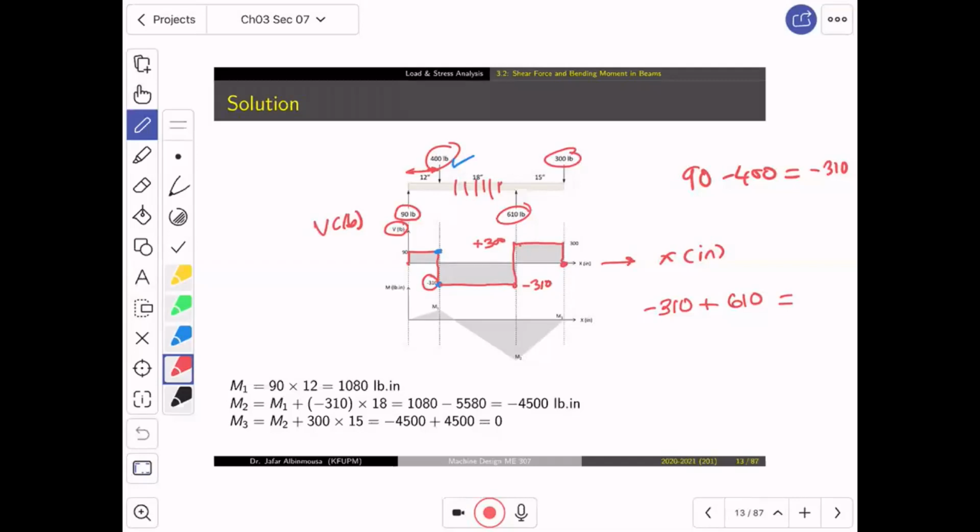If you recall in CE, they told you the shear force diagram has to end with 0. If you do not reach 0, then there is something wrong. Go and repeat it again. Okay, everyone? Fine. Okay.